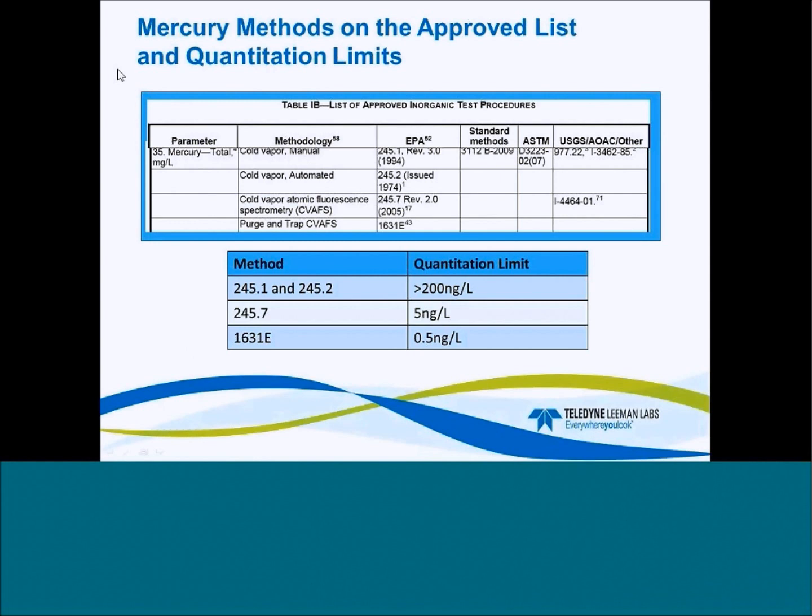From the actual Code for Federal Regulations sections, we get a table that defines what is allowed for mercury. And you can use 245.1, again, the cold vapor atomic absorption approach, or you can use two fluorescence techniques, 245.7, 1631.